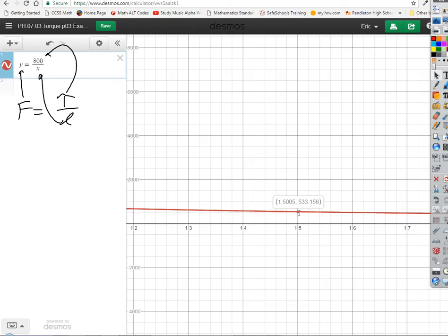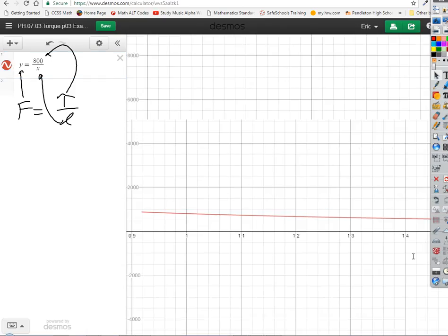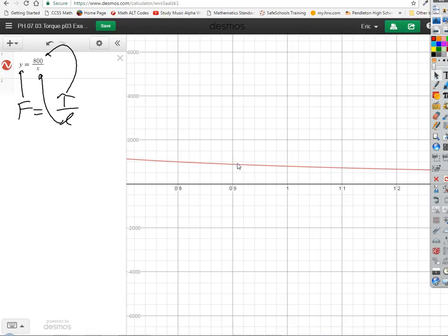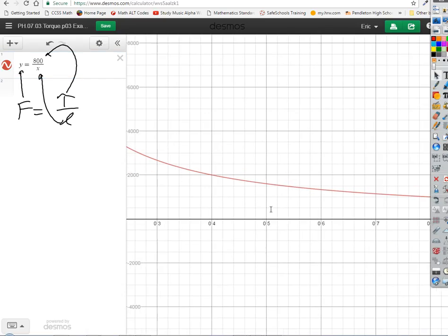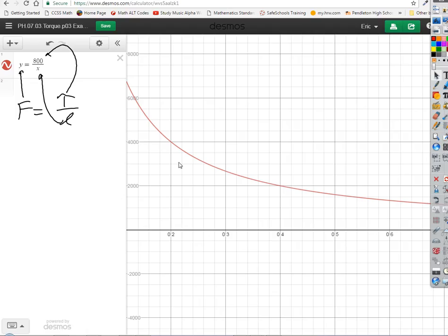Okay, so if you had a big trailer, without tires that big, you'd have a pretty hard time going up a steep hill, getting up that hill to the reservoir. But if we take it down to like 0.9, now that moves it up quite a bit. Now you're up to 890, right? And if you go down even smaller, this is getting kind of ridiculous, but if you had 8-inch tires on there, you've multiplied that up to 4,000, right? Okay, so it gets a lot bigger.